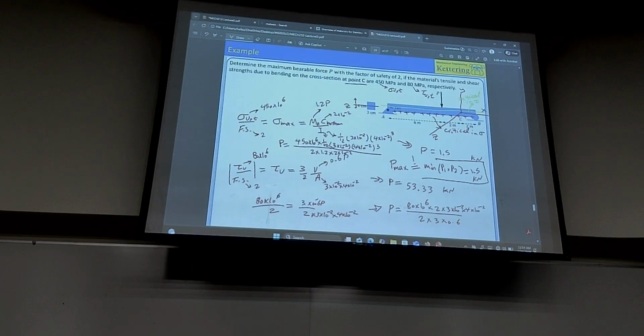Yes. So when we got FC and it's negative, since we assume the arrow is downward, does that mean it should have been upward because it was negative? Yeah, the load is the other way around, but because we're looking at absolute values, that's why I put the absolute value in here. But sign, in statics, just tells us the force is in this direction or that direction.